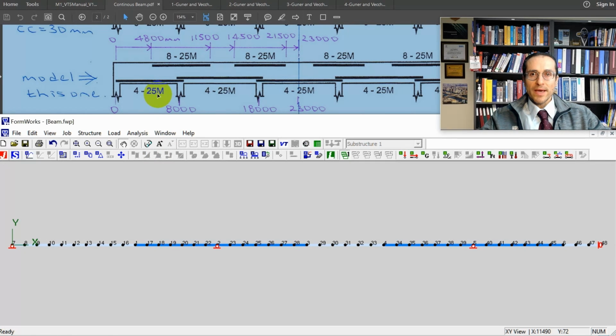When you are doing a nonlinear analysis, you do not want to do it for a single load value. You would always like to do a pushover because as you load the system gradually, you see the entire spectrum of responses. When is the cracking point? When is the reinforcement yielding point? Are there any shear cracking, any shear deformations, etc.? So you want to be able to see all of these versus just a single point.